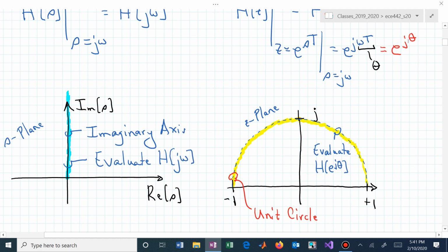Why is that? Well, that's what we're doing in this mapping. We won't necessarily get there today, but you can start to think about what frequencies we really have access to when we sample something. We only get up to frequencies equal to half of the sample frequency, omega sub s over 2. That puts us around to this point of -1.